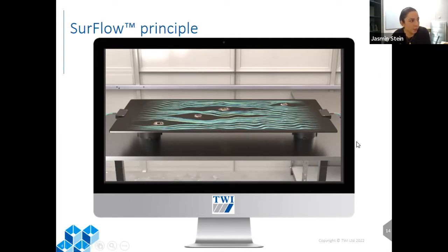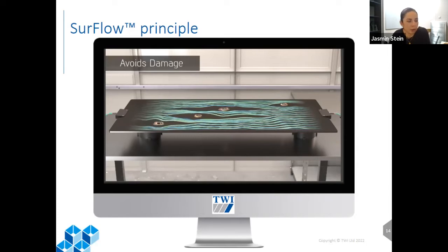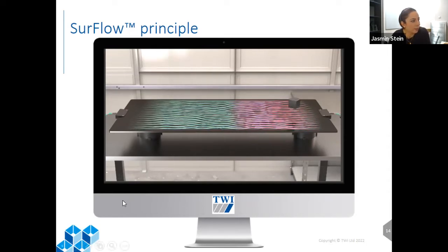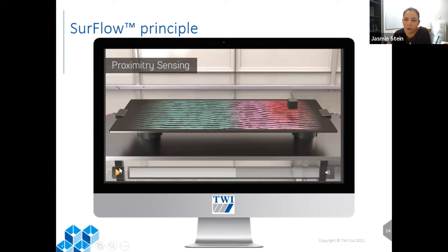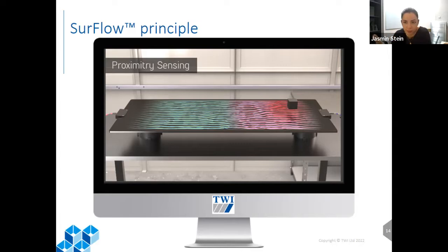And this is an obstruction. This one is an actual damage, and the signal still finds a path. Although the signal still propagates, there is a change in the signal signature. So other than using it to carry data, if you want to make your structure much smarter, you could use it for structural health monitoring, for example, and determine what damage there is and where it is. And that is through the change in the signal signature.